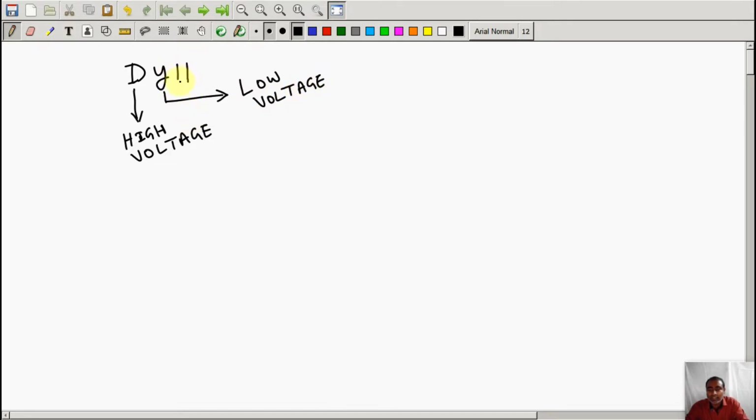And we can see digit 11 is written. Here digit 11 means that it is 11 o'clock. It is an interesting method of designating the phase difference between the line to line voltage on the high voltage and low voltage side in terms of the clock method of angle designation. Here we denote the phase difference between low voltage and high voltage side of the transformer in terms of time in the clock.